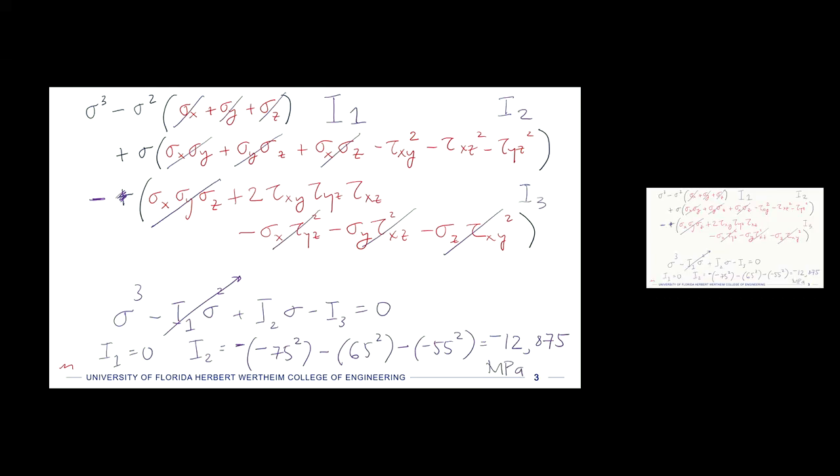Megapascals squared. Keep that good. So if all of our shear stresses are in megapascals, we took the square of all of them, added it together. We have megapascals squared. And that makes sense if you go back up to the generalized equation, because that is times a normal stress, our sigma that we're going to be solving for. So each term in the generalized stress equation has the units of megapascals cubed. So that's what each term has to have overall. So our coefficient has megapascals squared times megapascals of the sigma, and we get to the cubed. So we have first invariant, second invariant. Now we need the third one.